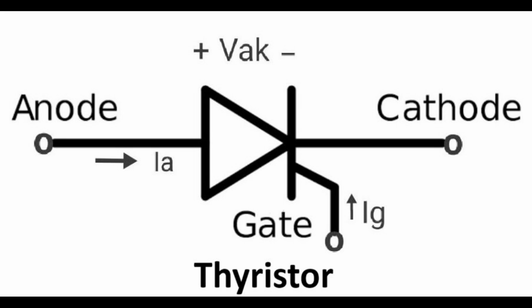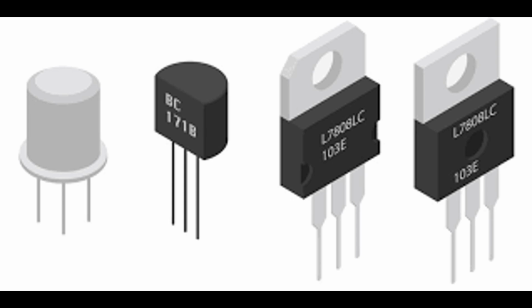Advantages. High power and fast switching. Combines the high power capabilities of thyristors with the fast switching of MOSFETs. Efficient control. Offers precise control over switching, improving the performance and efficiency of power systems. Simplified drive circuit. Easier to control than traditional thyristors, reducing the complexity of the gate drive circuitry. Bidirectional control. Can be designed to handle bidirectional current flow, making it versatile for various applications.